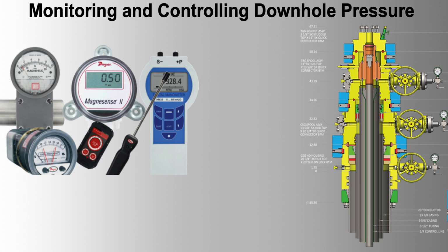Example issue 4. Corrosion of downhole instruments. Problem. Corrosion of pressure sensors leading to inaccurate readings and potential failure. Solution. Replace sensors with models made from high-grade corrosion-resistant materials like Inconel or Hastelloy. Implement chemical treatment programs to reduce corrosive elements in the well.